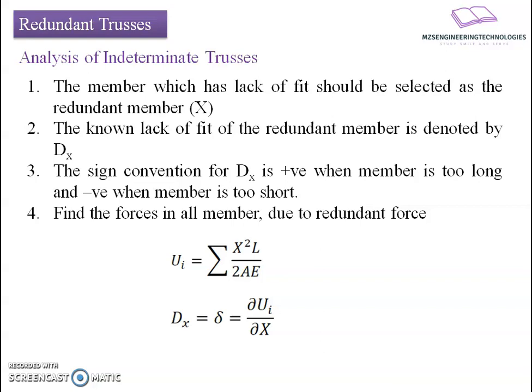We were discussing the effect of lack of fit in statically determinate trusses and statically indeterminate trusses. In the last lecture we dealt with statically determinate frames, and we came to the conclusion that the lack of fit will cause deformation of the member, but it will not develop any stress component in case of statically determinate frames.